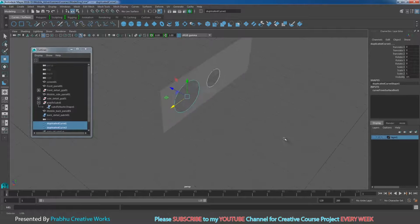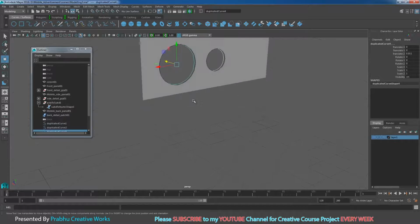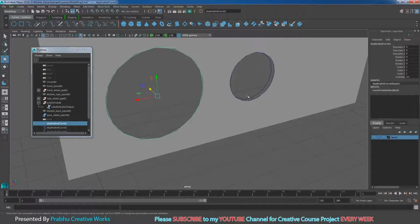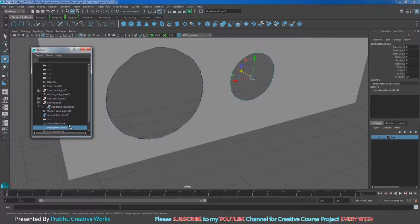Now with both curves selected, press Ctrl D on the keyboard and move a little bit further away. See here you got a lot of jagginess, so don't worry. I will select this one and press delete. I will select this one and press delete, so you have only two curves.